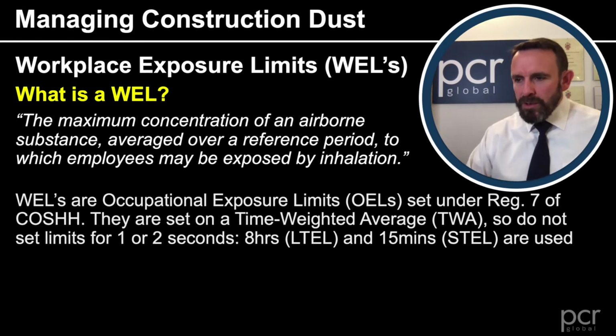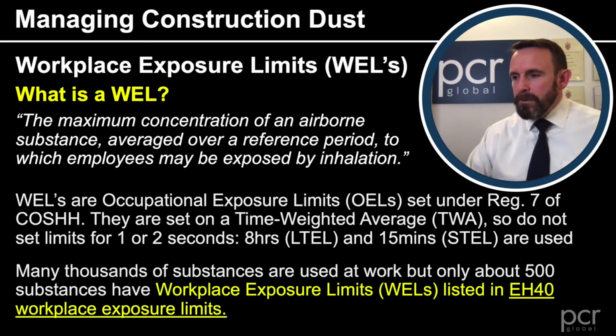So WELs are occupational exposure limits, OELs, and they're set under Regulation 7 of COSHH. They're set on a time-weighted average, a TWA, so they do not actually set limits for 1 or 2 seconds, but they're set either on an LTEL, a long-term exposure limit over 8 hours, or on an STEL, which is a short-term exposure limit of 15 minutes. Many thousands of substances are used at work, but only about 500 substances have actually been set WELs, and they are listed in EH40 for workplace exposure limits.